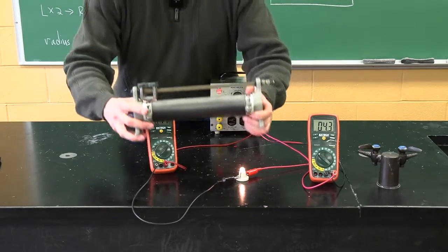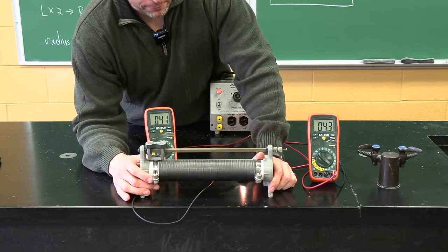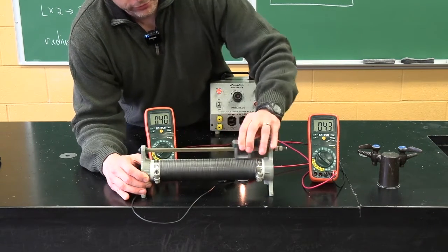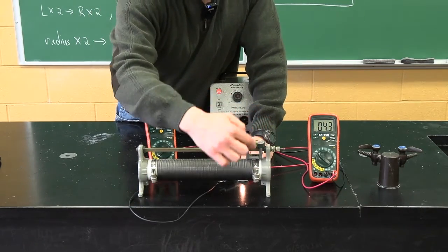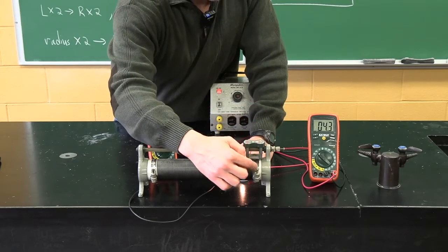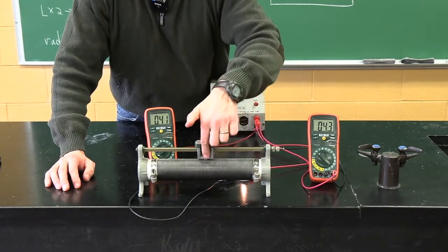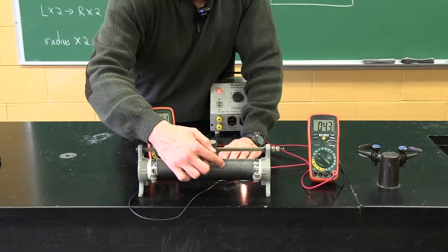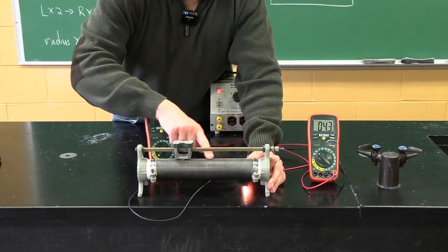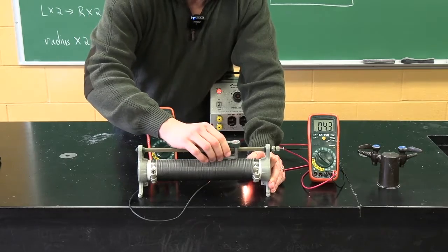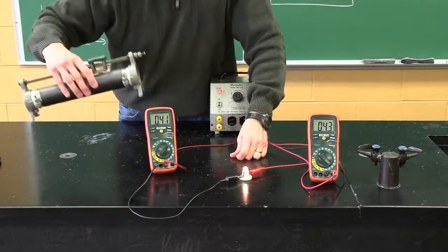Well, one ingenious device is this device right here. What it does is it basically creates what we call a variable resistor. If I hook wires here and here, there's very little resistance because the electricity can just go through this post down to this point right here. But if I go like this, the electricity now gets deposited at this contact and has to spiral through all this wire before completing the loop. So by sliding this, I force the electricity to go through more wire or less wire, more resistance, less resistance. So I'm going to insert that into the circuit now.